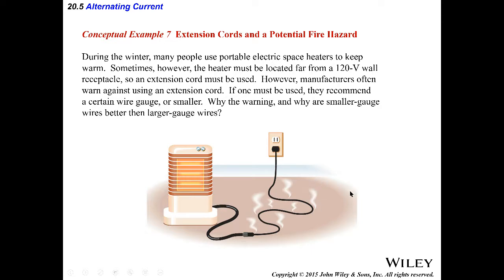I squared R. And now, when my current is big and my R is also big, this can cause a fire. All right? So just be aware that you should always use what they call recommended, namely a thicker extension cord, not a thin one.